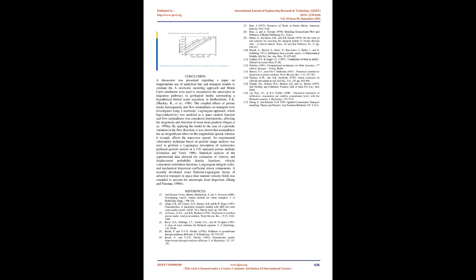By applying the model to the case of a periodic variation in the flow direction, it was shown that unsteadiness has an insignificant effect on the longitudinal spread, whereas it strongly affects the transverse spread. An experimental velocimetry technique based on particle image analysis was used to perform a Lagrangian description of non-reactive pollutant particle motion in a 3D saturated porous medium, Sindis and Viotti, 1996.